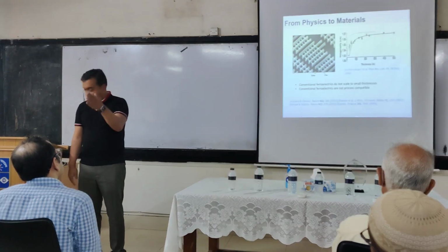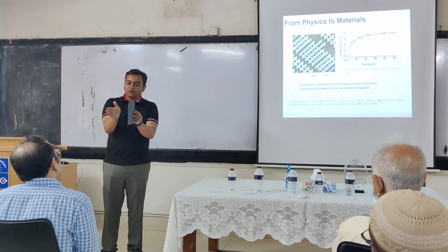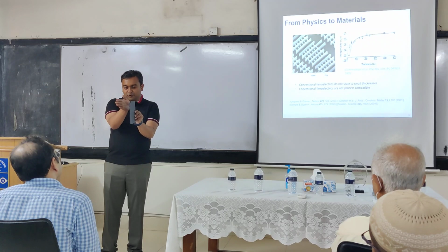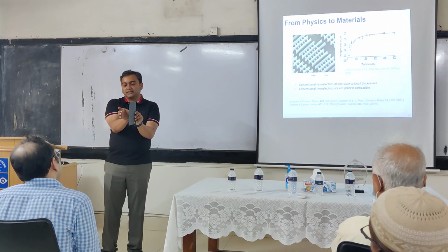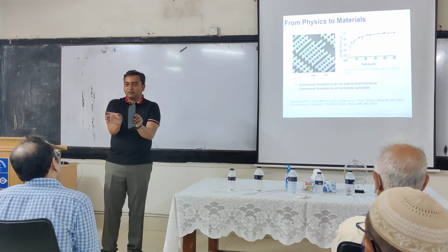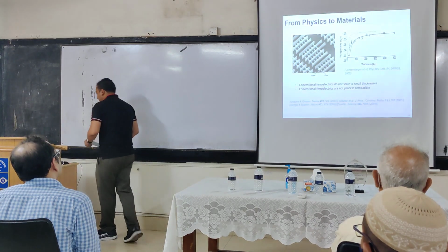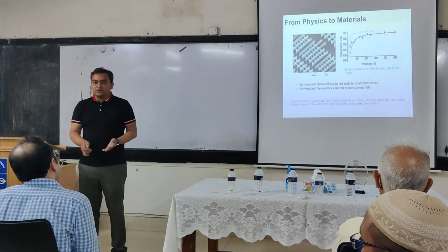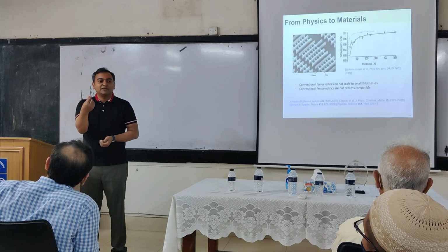So think about it. A FinFET looks like this. This is the fin. There are two of them, 29 nanometers apart. You have to put a gate oxide like this. On top you have to put a metal, like this. When you put things like this, it forms on this side wall, and it forms on my hand as well. So if you put 5 nanometers of metal, then it is 5 nanometers here and 5 nanometers here, and you have already taken 10 nanometers of the 29. If your gate oxide is 2 nanometers, you have already taken 4 nanometers. So you have now taken 14 nanometers of the 29. But you have to put a metal connector, right? If you make a metal which is 10 nanometers thick, the metal does not remain a good metal.